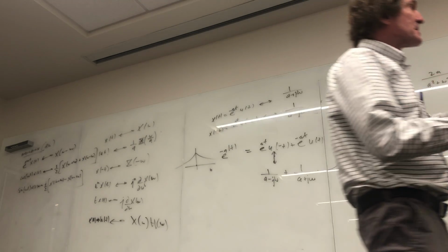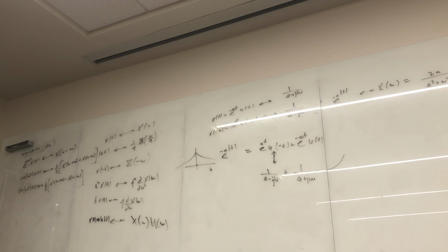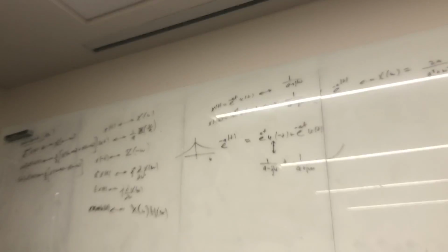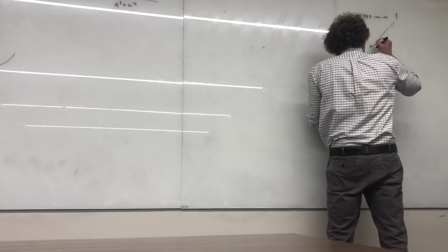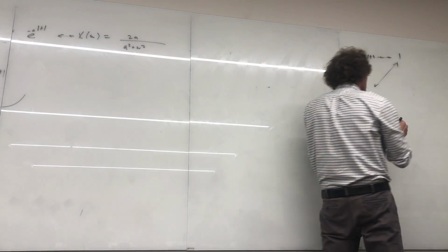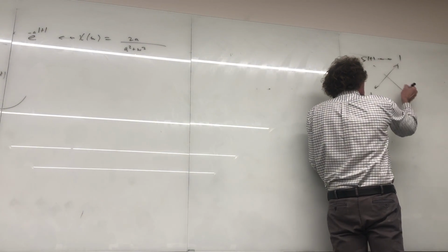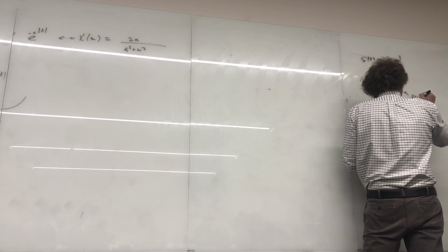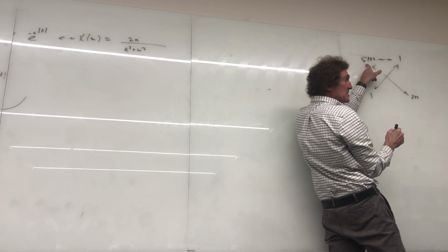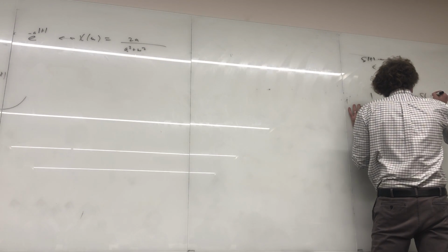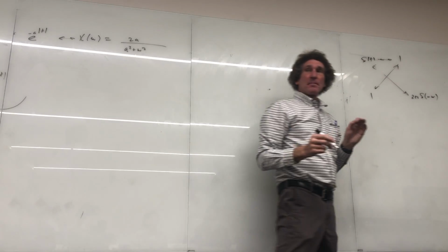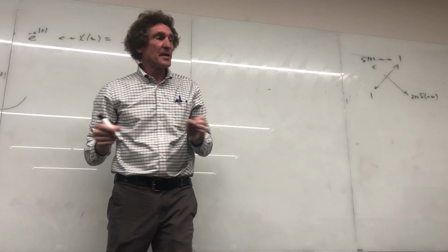If we know a delta function goes to 1, this is so important. You know a delta function has a transform of 1. And we can take 1, therefore, and make that our time domain function. And then out here, I have to take 2 pi, and I replace t with minus omega, right? Y'all remember doing that? Critical that you do.